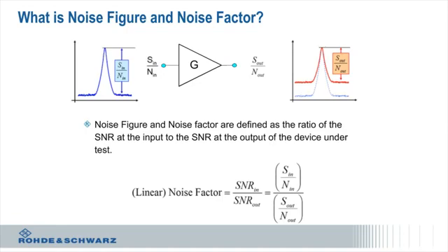Okay, so what is noise figure, noise factor? It's a ratio of how much noise is really added by a device, and it's typically going to be an amplifier. Okay, so you see the signal-to-noise ratio in over the signal-to-noise ratio out.